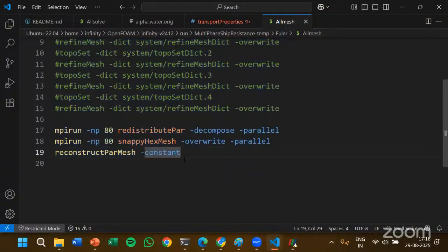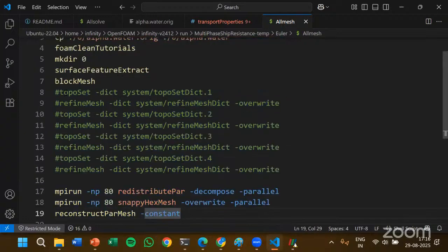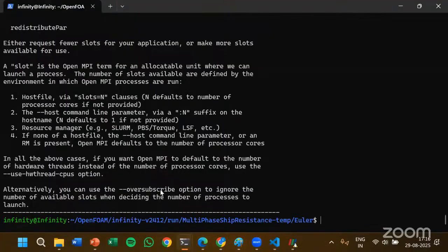Since we've made the mesh in snappyHexMesh, it will start with your surfaceFeatureExtract, then it will create a blockMesh, then we'll go ahead with decomposing the whole thing. Now in our case, since we ran this case, it will give me an error. Yeah, you see it's given me an error. So before you run any of these simulations, it's always better to open these Allrun and Allclean files.